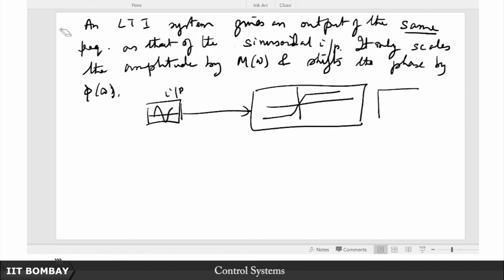If the amplitude of the input is very large, then in the oscilloscope at the output port, you will see that it has got clipped like this. So therefore this obviously has frequency components. If you do a Fourier series analysis of this periodic signal, you will see that it has not only the fundamental harmonic, but also many other harmonics. So you give an input of just one frequency, but at the output you have several other frequencies appearing,